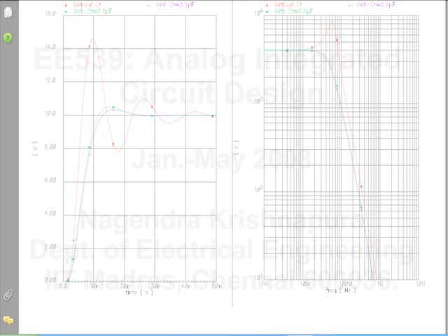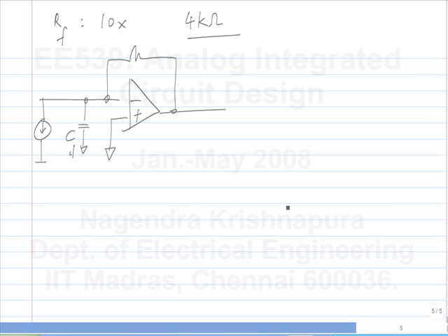No, this is because I used the same current step that I had used for 400 ohms. So, I mean, I used the 2.5 milliamp step and I didn't change it when I changed the trans resistance. So that's why, I mean, you should mentally scale this by a factor of 10. Okay. So, okay, it rings like mad. So, what do we do to fix this?